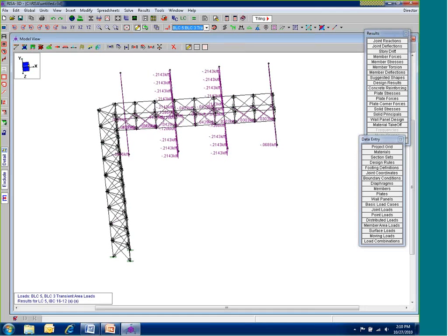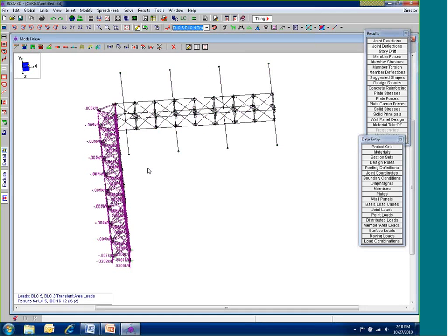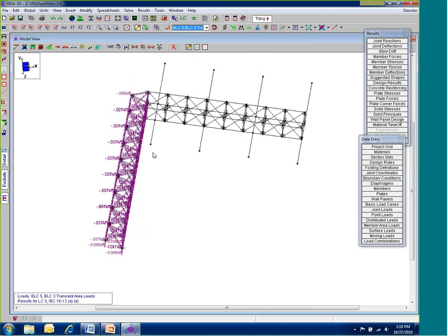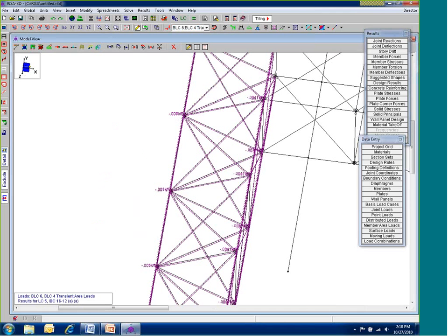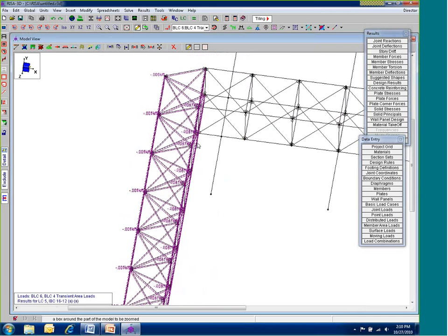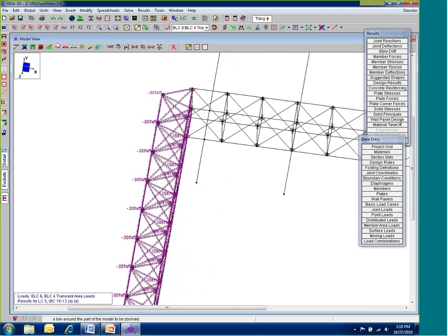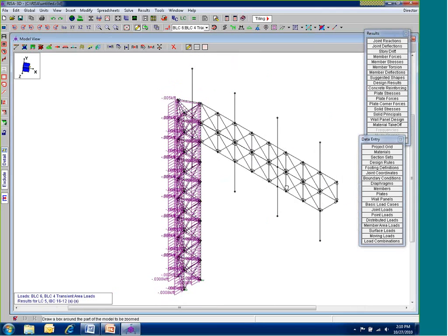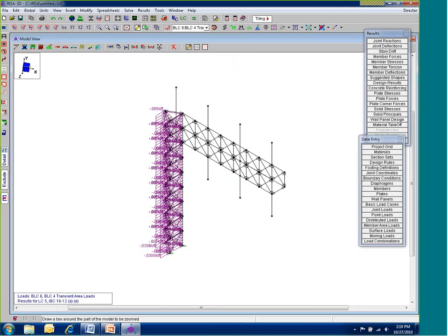And if I look at here on the wind on the actual structure, I see I get wind directly on the structure there, and we see that when we put that wind load on there, it breaks it down into a line load that we can even see a little bit farther per each member. Okay, so definitely something that you want to look at and make sure that you did the loading the way you thought you were doing it. Okay, so we've got all that laid out, and basically that would be kind of the end of this model. We would probably go through and make sure we sized up our webs a little bit. But I think we've covered a lot of the different topics we've got here.